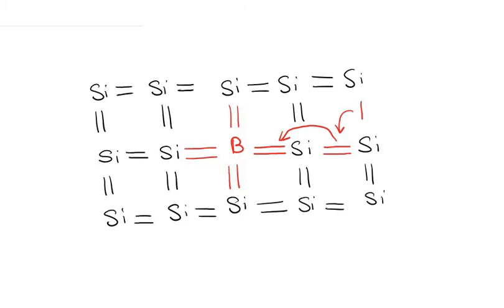That is why they are known as acceptor type impurities, because a boron atom has 3 electrons in the valence shell, so it can accept 1 extra electron and form a complete bond with the neighboring silicon atom. Since it is accepting 1 electron and forming the 4th bond with the neighboring silicon atom, these are known as acceptor type impurities.